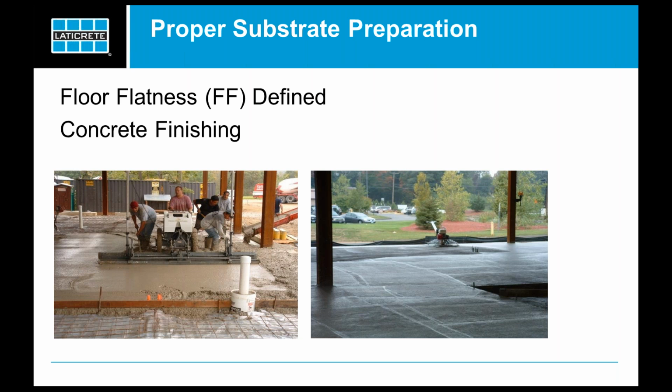With smaller tiles, you could probably hide some imperfections and irregularities in a substrate, but with these large format materials, you really cannot hide them. So we want to talk about floor flatness a little bit, and we want to see how that correlates to the tile industry, and it helps us get the installation on the right foot.